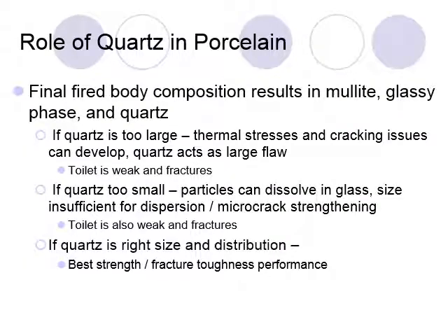So for porcelain, and you could find papers on this, the final fired composition has a number of phases. There's a glassy phase, there's a mullite phase, and there's the quartz. The quartz size affects the thermal stress, it affects the strengthening, it affects the crack behavior, and has a large effect on the behavior of the toilet bowl in terms of strength. So you have to have the quartz as the right size to have strong toilets that would be mounted on a wall like you have in a hospital or facilities like that.